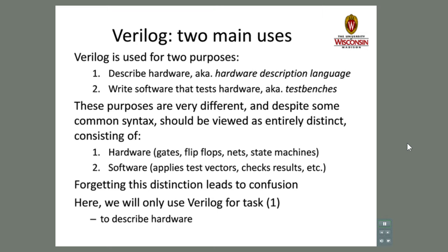Sometimes this distinction is described as synthesizable Verilog versus non-synthesizable Verilog, which in itself is confusing, but is intended to convey the idea that some Verilog features cannot be practically converted or synthesized into digital hardware and can really only be used during simulation.